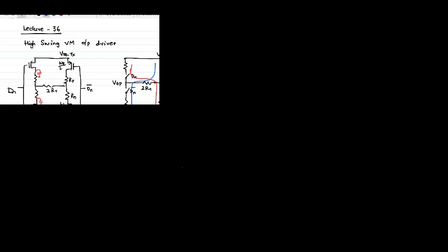The internal node parasitic capacitance will cause a data dependent output, which is like CP1 and CP2, whereas the input capacitance, let's say CP3, will cause more power consumption in anything which is driving it. So there is a trade-off in both cases.